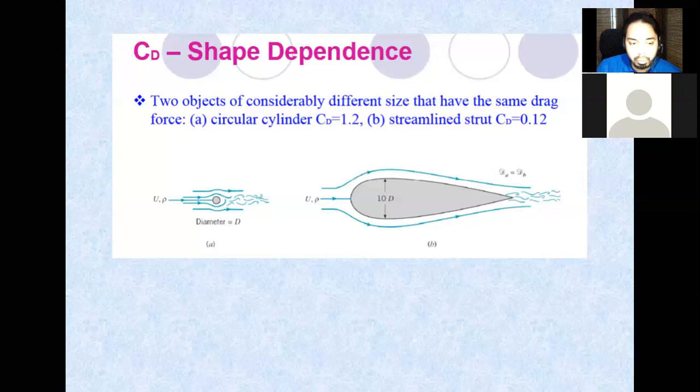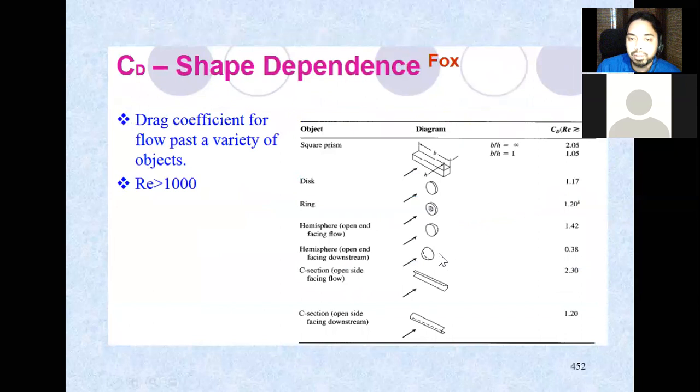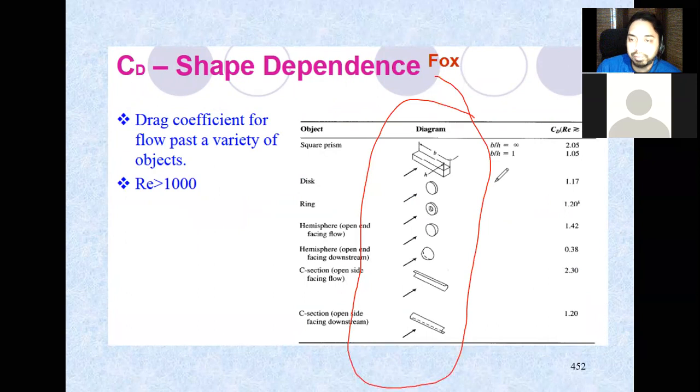So yes, shapes determine the drag force also. This table gives you drag coefficient for different shapes. You're able to use it to solve, for example, for different shapes. Apply for Reynolds number greater than 1000.